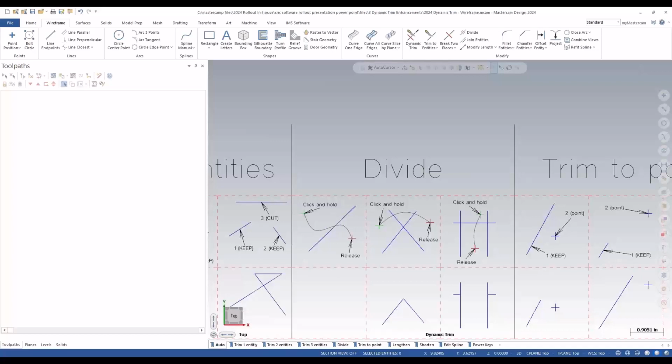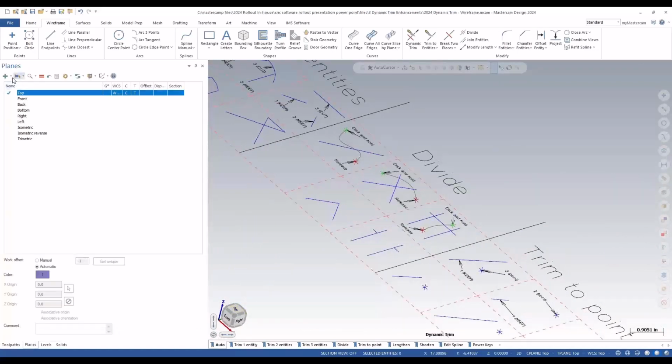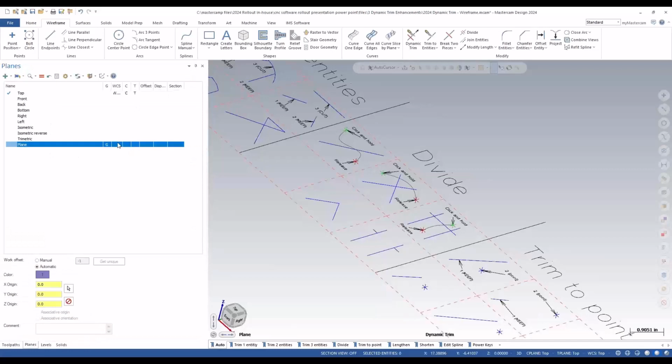Okay, there's a few more questions here now. Can we rotate the cube and create a new plane? I think he's talking about creating a plane from G view. Oh yeah, you can rotate this cube, and then if you wanted it on that exact view, you could come into planes and select the option from G view, and it'll grab that plane, and then you've set that plane.